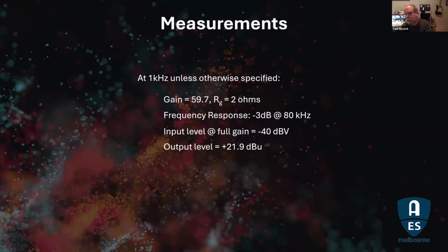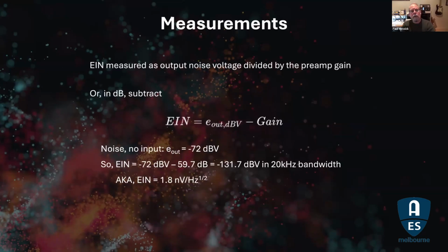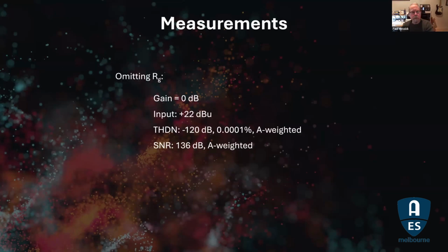It doesn't make any difference with high gain, of course, and it did make a difference at 0 dB gain. It's 6 dB worse. So, sorry, 3 dB worse because it's summed as a square. So the noise got 3 dB worse at 0 dB gain. So since the OPA1612 has no problem driving 1K, I've left it at that. Does that make sense? I think it was Greg that asked that. Good catch. Where are we? I'm lost. Help.